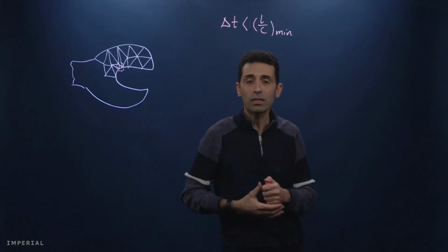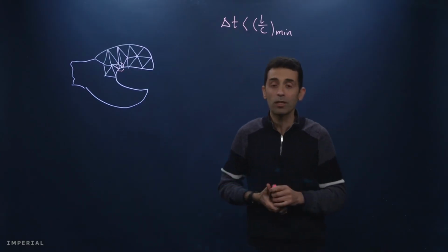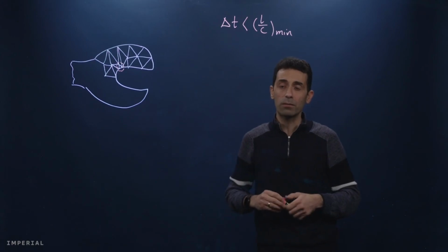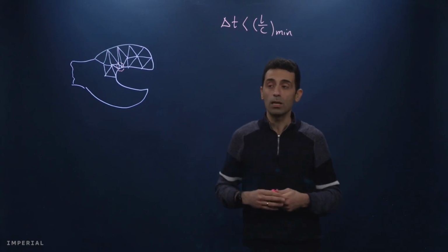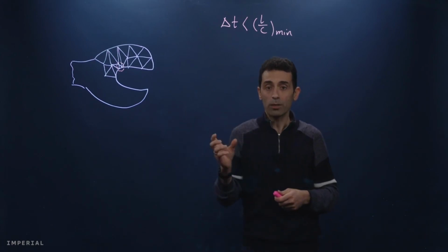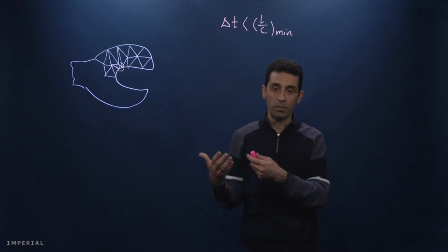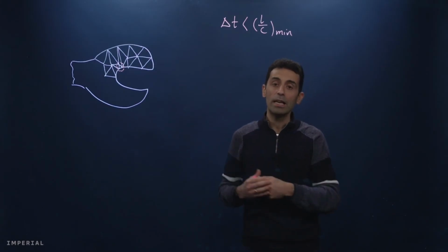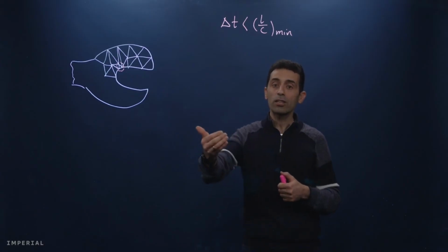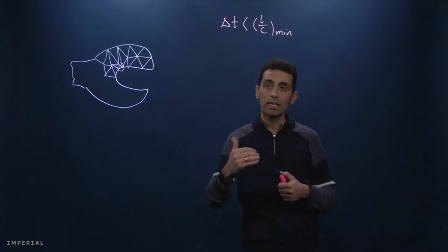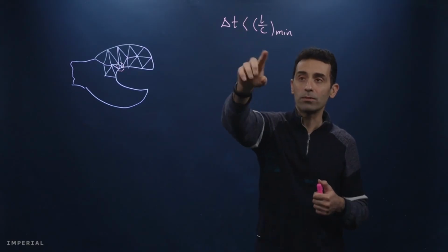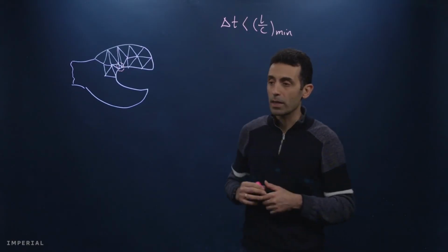Stress propagation in that part may not be important. You may not even be concerned about the fracture of that part, or it may not fracture at all. So there might be an opportunity to make that part rigid. If you make it rigid, of course theoretically rigid, then the software will not include that part in the calculation of this bound for the delta T.